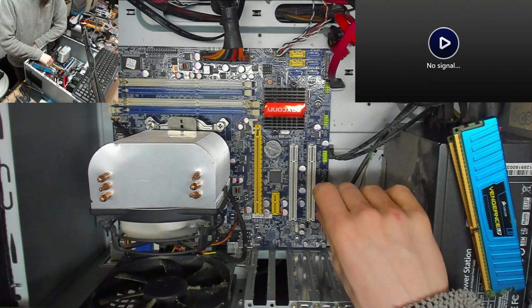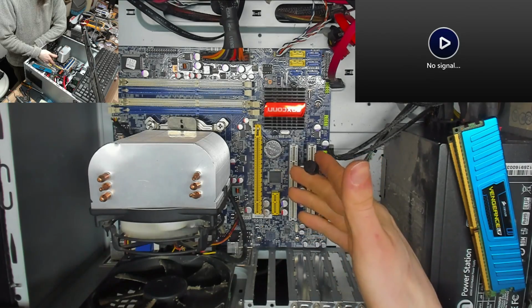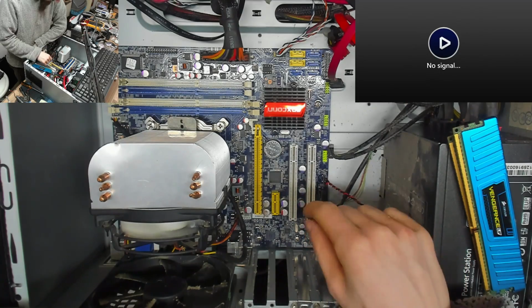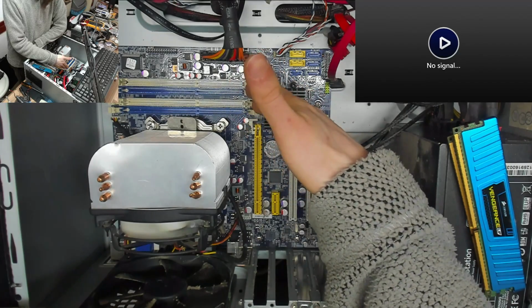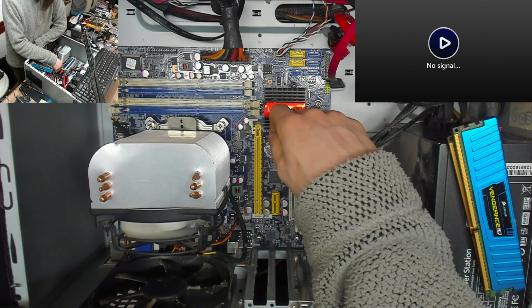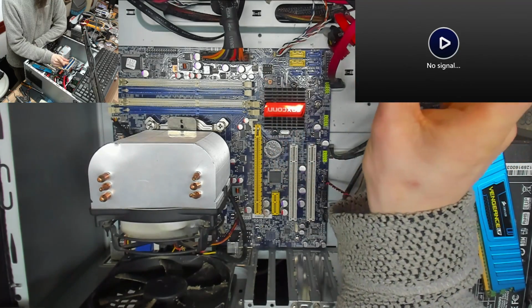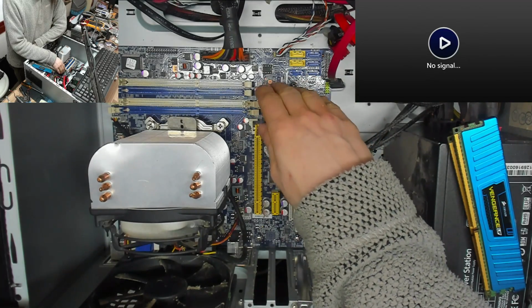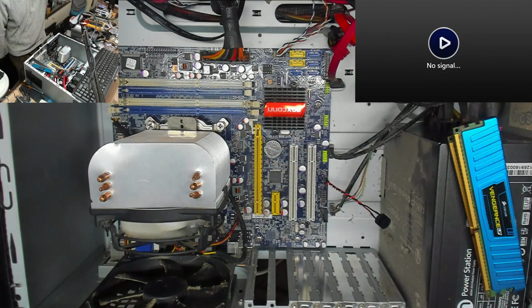Right, we're getting no beep at all still. So the fact that it's not beeping with no RAM in it at all, when we've got our beeper connected and we're getting nothing out of that, generally implies that there's something very low level wrong with this, because it's not even getting as far as to check the RAM. So I think we're down to CPU or motherboard here, and it's never the CPU except when it is. I tell you what though, I think I might have a spare 2nd gen Intel CPU knocking about in my spares box. I'm going to have a quick look for that.